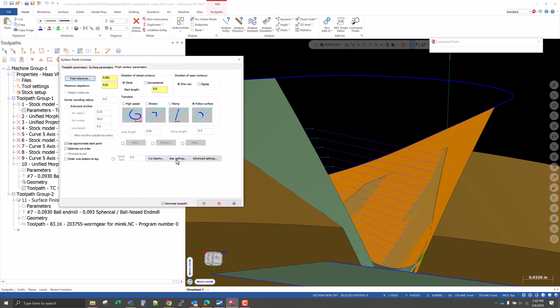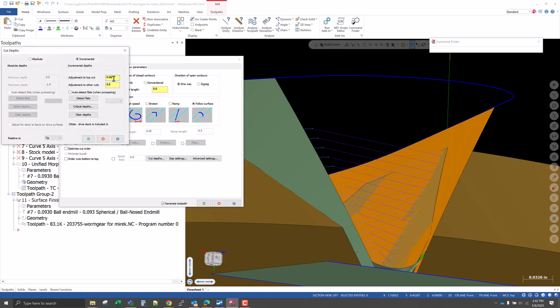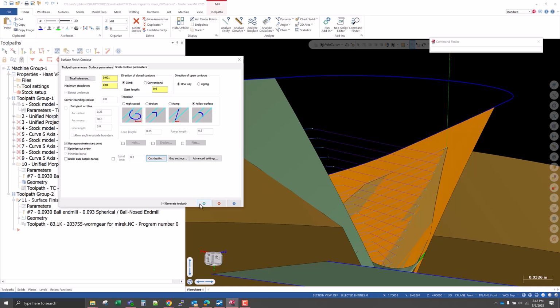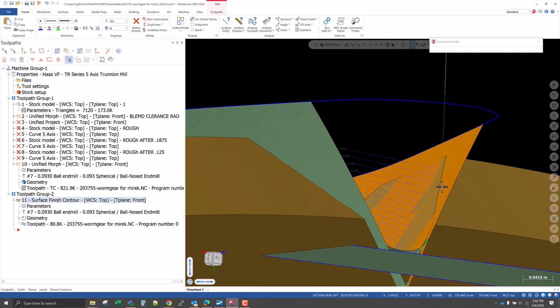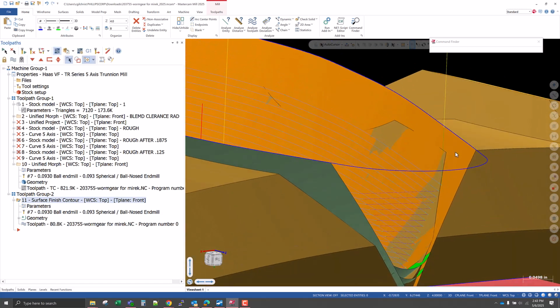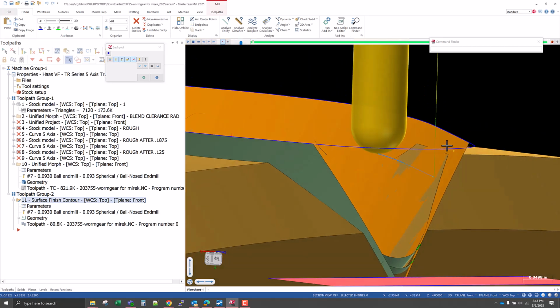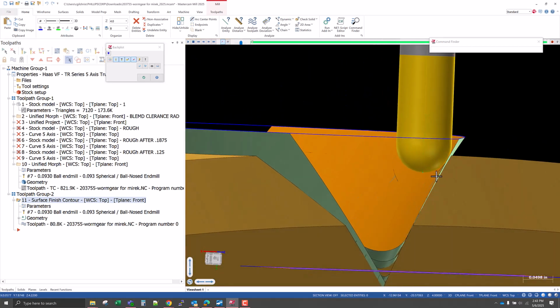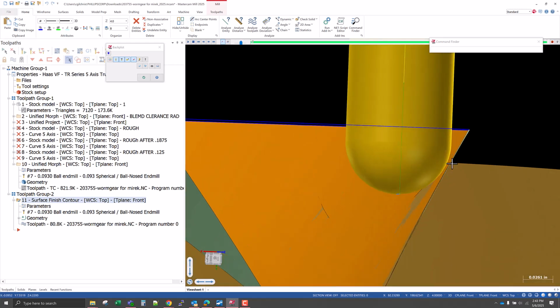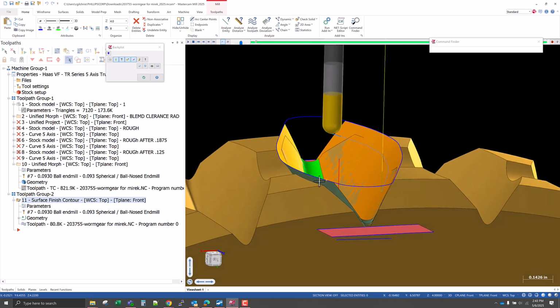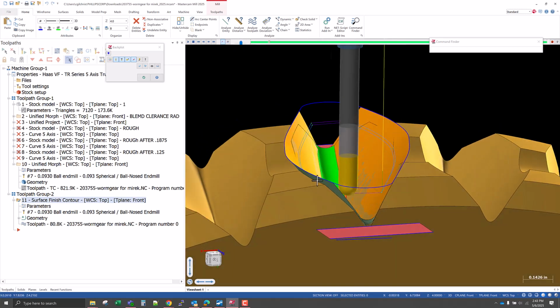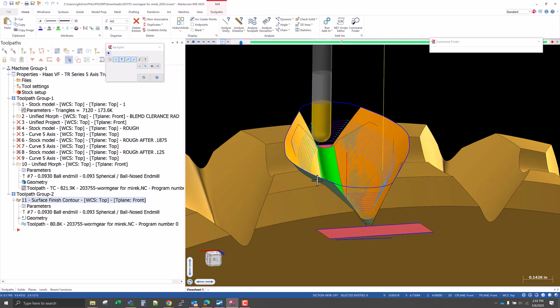If I go back in here and say, okay, cut depths 0.06, you can see it actually dropped that starting pass. So now we're starting a little more down there, but still should be in a good spot. You can verify this, you can run it through and look at the material that way. But this is going to give us such a nice, clean toolpath.